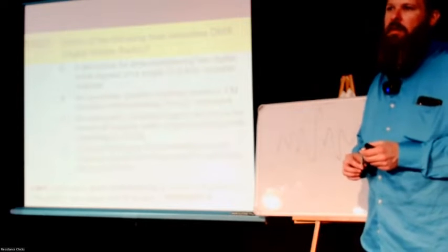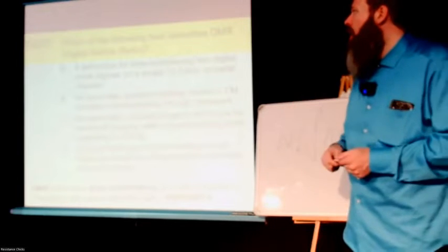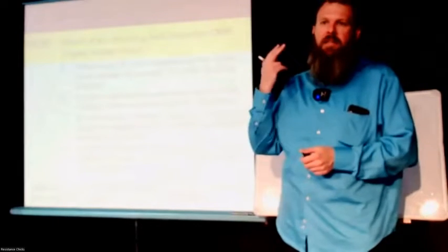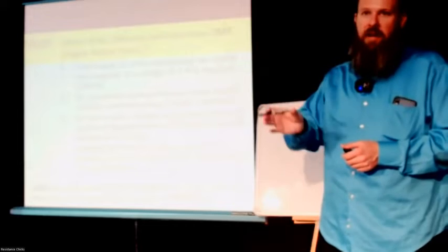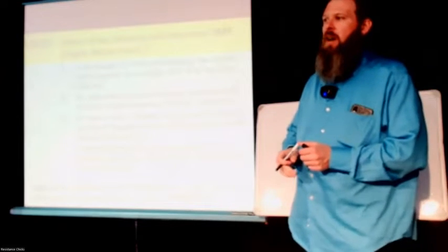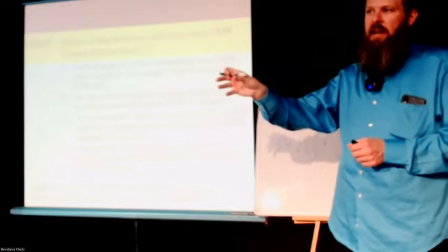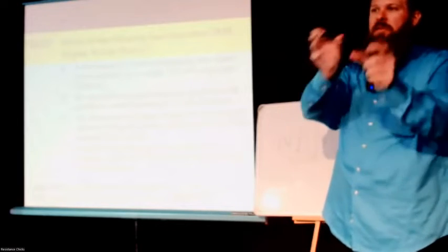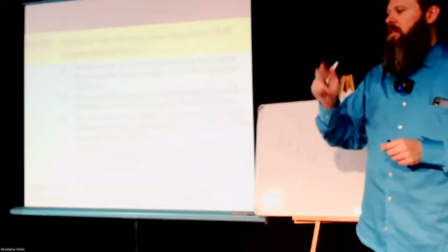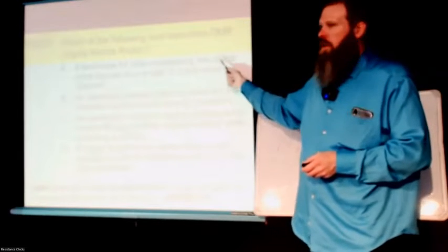If you remember, on the first day I talked about DMR and how it can hold two simultaneous conversations because it has a time slot 1 and a time slot 2. Depending on which time slot you are in, it will drop your digitized audio in that time slot, and then in the very next time slot it will drop the other person's, and it keeps alternating and allows two simultaneous conversations to happen. That's what it's describing here. So hopefully you will remember that.